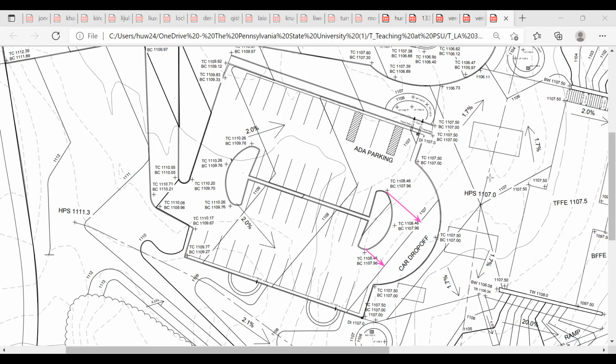Yes. Okay, yeah, use those. You can set up a spreadsheet, set up the equation, measure this distance, and then do the calculations. And make sure that you always go in one direction, right? If you want to go downstream, measure to the lower contour, you add 107, right?